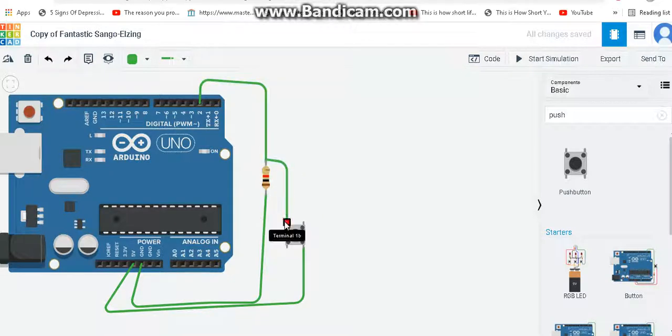So for example, this point and this point, one is A and one is B. Okay, and like that. So I gave some point names to the place in between the resistor and ground, and to the place where the resistor meets the wire from the switch. So likewise you can remember from the previous video A, B, C, D, E, and then you can create the connection. A is going to this pin, B is going to +5, E is going to ground, like that you can create the circuit. Okay, so look at the diagram and create the circuit.